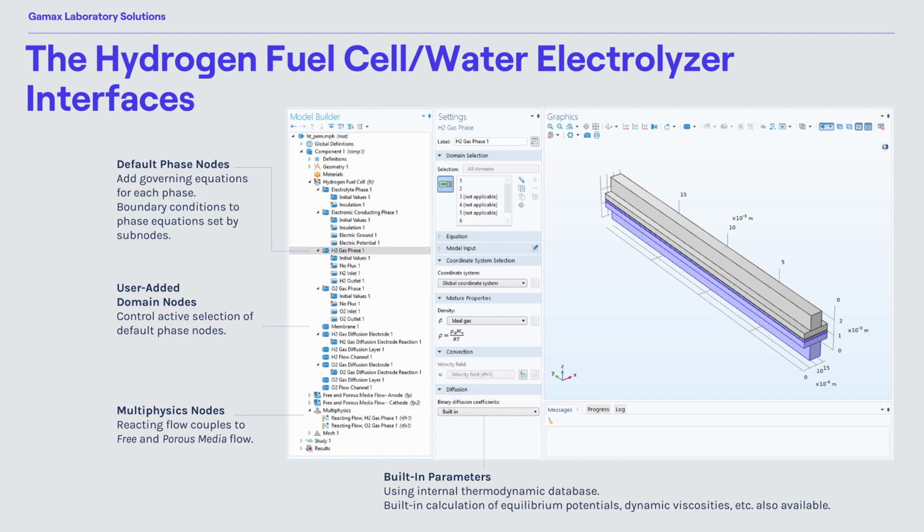If required, you can add more boundary conditions or domain conditions based on the model setup, whether you want to add active cooling, an active flow of materials, or maybe this will be a passive element, so that's not really necessary. Or if it's a thin layer where the mass transport is negligible from the modeling side, then you can replace the volume conditions with surface or boundary conditions, so you can speed up the computation. That's just one part, the fuel side itself, solving for the chemical reactions, the reaction kinetics and the other coefficients.